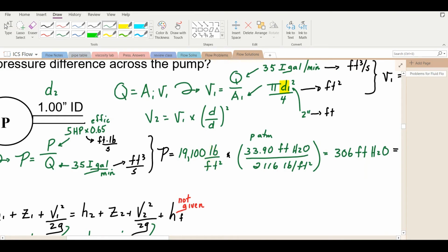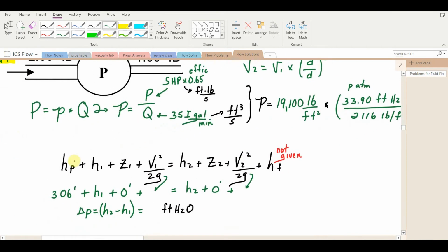But you can't put that unit into Bernoulli's equation. In this form of Bernoulli's equation, each term is in height of a fluid, the height of the fluid in the system. If you'd use the other form of Bernoulli's equation, in which all terms are units of pressure, you could put this value directly in, but not in this case. You'll have to convert it to height of fluid.